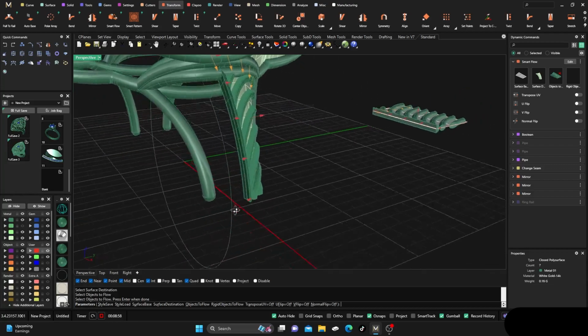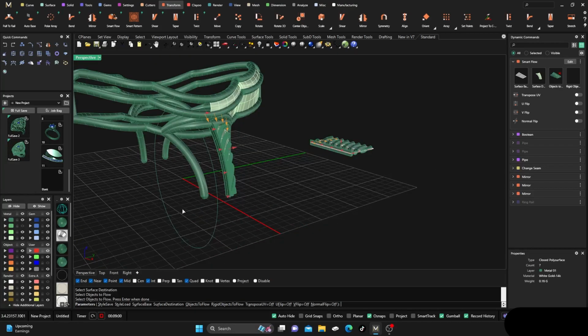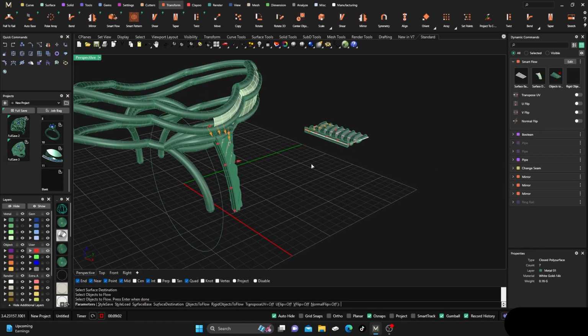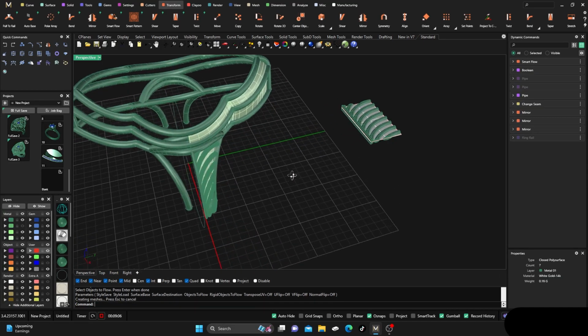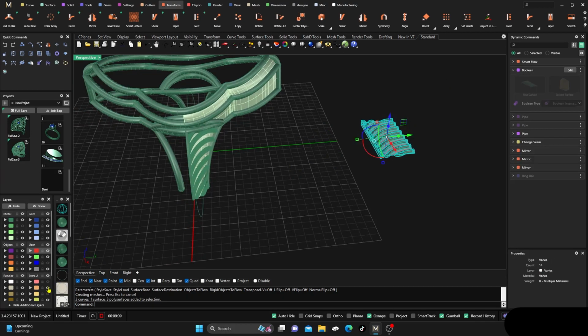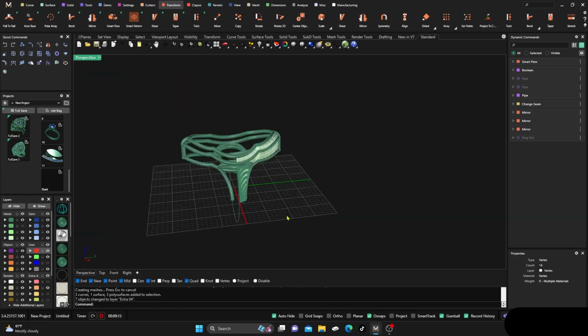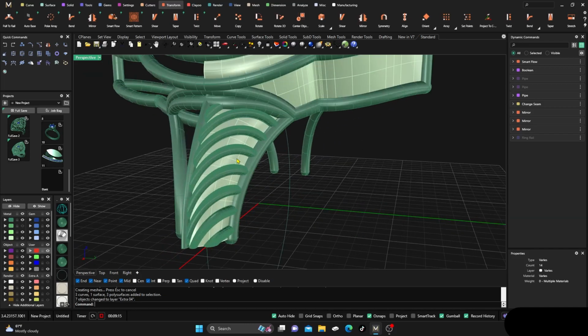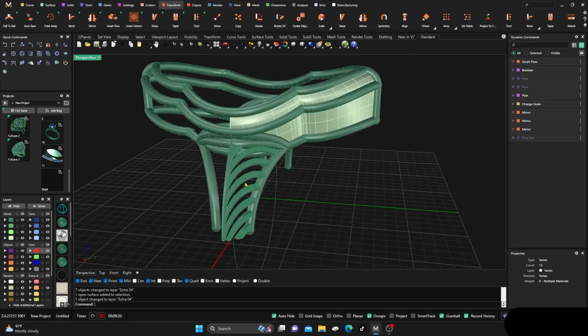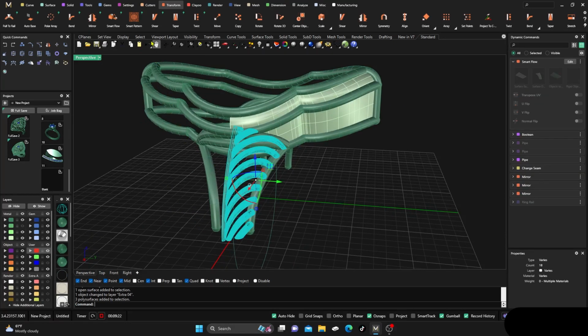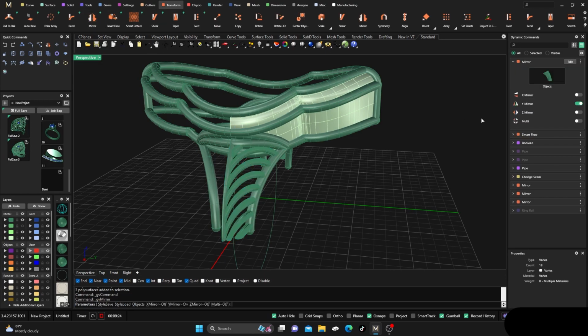What happened to my curve there? I had a curve here at one time, I thought. Okay, so we'll hit enter. That's what we want. And we'll take all this and hide it to this layer here and get rid of it for right now. And we can go ahead and get rid of that surface there as well, because that's kind of what we wanted. And we can take all this here and go to transform, parametric mirror, XY on, multi on, and then enter.